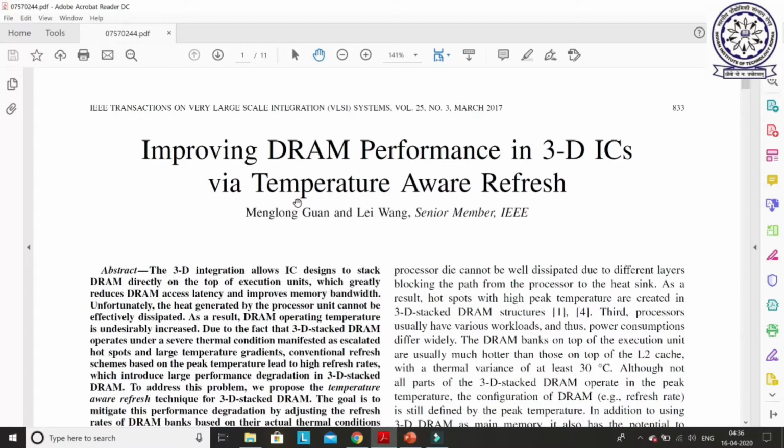Once you understand what DRAM LLCs are, how they work, and the recent advancements, you will find other work combining the concept of DRAM LLC and SRAM, or combining DRAM LLC with non-volatile memories, and those fall under hybrid LLC. So not just hybrid LLC, hybrid cache memories.